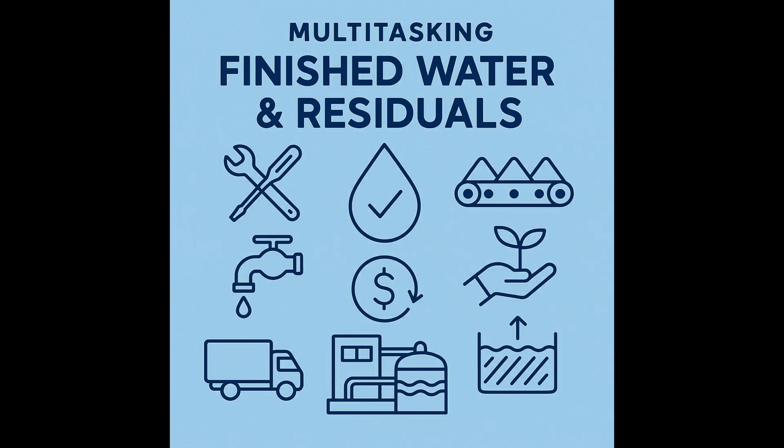And integrating all this with the plant's main control system, the SCADA or PLCs, programmable logic controllers, allows for automated pump speeds, chemical feed rates, alarm notifications. So less manual tweaking, fewer errors. Definitely. Less operator time spent babysitting the residuals process, less chemical waste, less equipment downtime. Paybacks for automation projects in residuals can often be in the 2 to 4 year range, which is pretty attractive.